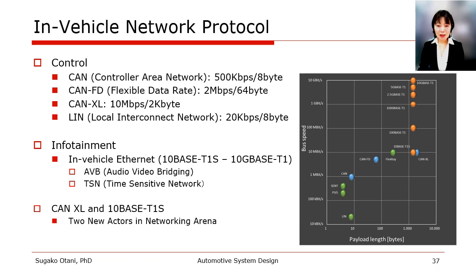Aided by this technology, control and advanced driver assistance system (ADAS) functions or automated driving (AD) can be realized, connecting cameras and other sensors, actuators, and data processing ECUs to a switched Ethernet network.